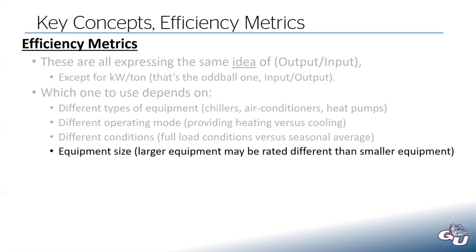The equipment size can make a difference. Larger equipment may be rated differently. So for example, larger cooling equipment, the typical seasonal average metric is IEER, but smaller equipment is rated on SEER.